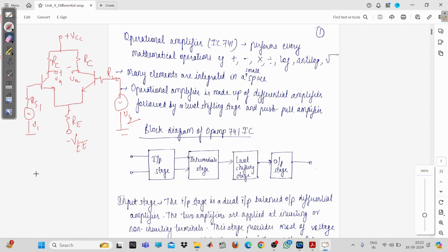As told earlier, for a good amplifier, you will require four important things. That is, you require high voltage gain, then you require high current gain, then you require a high value of input resistance and a low value of output resistance. These four things you need to consider while selecting the common emitter configuration for the amplifier. Fine. So now coming to the unbalanced output.